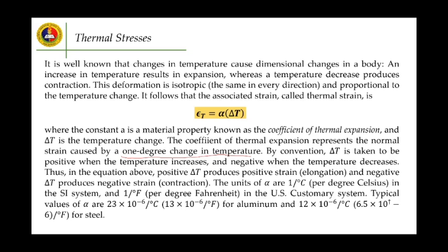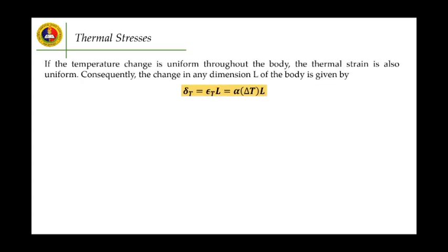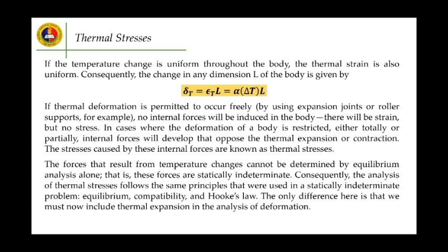But nevertheless, in all of the problems provided, the coefficient of thermal expansion will be given. However, what is required from everyone is to analyze the temperature change and analyze how a material will deform subjected to that given temperature change. Now, if we are talking about the thermal strain, if the temperature change is uniform throughout the body, the thermal strain is also uniform. Consequently, the change in any dimensional L of the body is given by